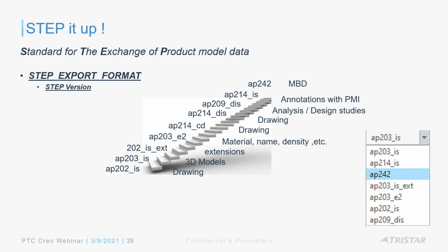STEP itself has gone through a lot of versions over the last few years, and the latest one, AP242, is something PTC has been supporting starting with Creo 4.0, especially for MBD, model-based definition. It's very significant, wherein you're able to add those annotations, and the STEP AP242 version is able to hold those.